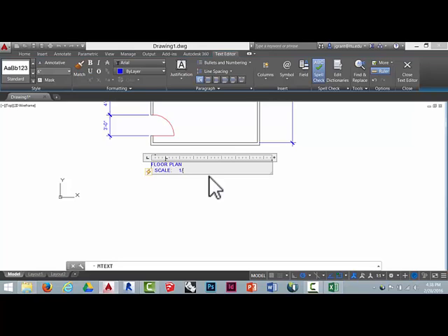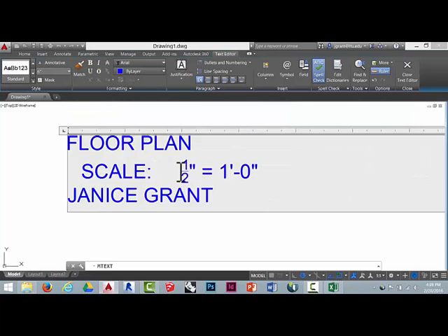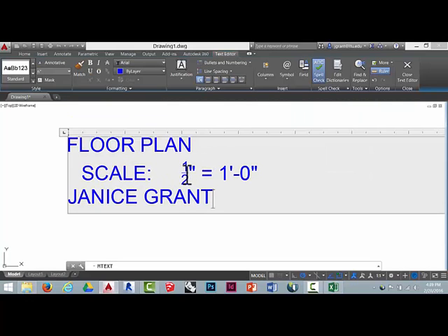In these newer releases of AutoCAD, the numbers are automatically stacked, and you do have that automatic indent. I'll show you how to fix that if you like. You see this? It'll automatically think that you want to put another scale there. So what you can do to clean that up, if you don't want your fractions stacked, because they do get pretty small, depending on the scale that you print, you can click on that fraction and click right on that little lightning bolt icon and pick unstacked.